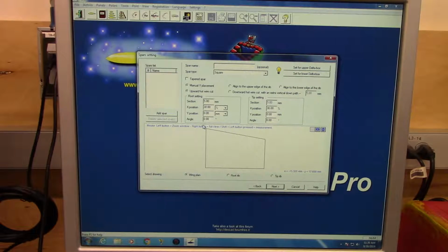Under the spar list, Profili will code in for you a way to cut out holes for spars if you need structural reinforcement for your wings. Your tail surfaces don't always need this. Oftentimes they're small enough that the physical properties of the foam will be sufficient to maintain structural integrity. But for an example, I'm going to throw one of them in here because oftentimes your wings are the opposite, where you do need a spar going in.